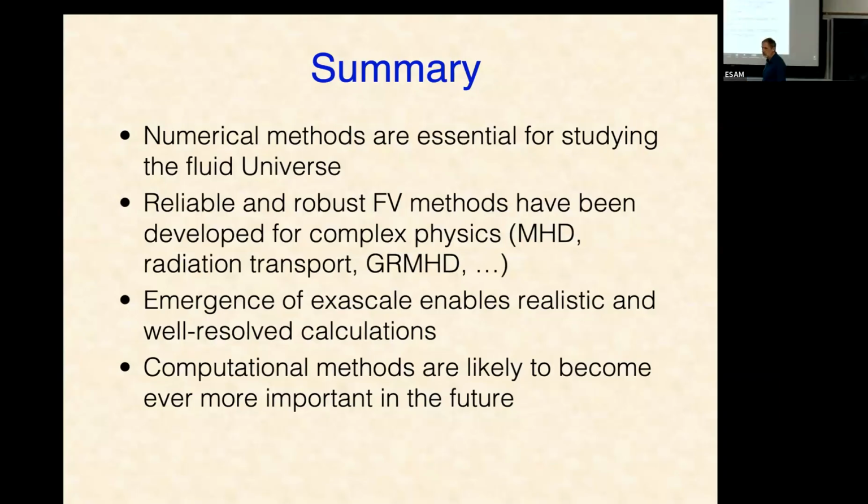When you talk about AMR, you describe mesh refinement, but what about the adaptive aspect? The adaptive part just comes from your decision about what properties of the flow you want to resolve better. Is there some value of the conserved quantities that would trigger refinement? You always refine regions where the density is above some value. So does that mean there's some gradient? That's completely up to you. You can have any refinement criteria you like. Once you've identified a region where your criteria is true, then you just lay down an extra mesh there. It's straightforward to do that.